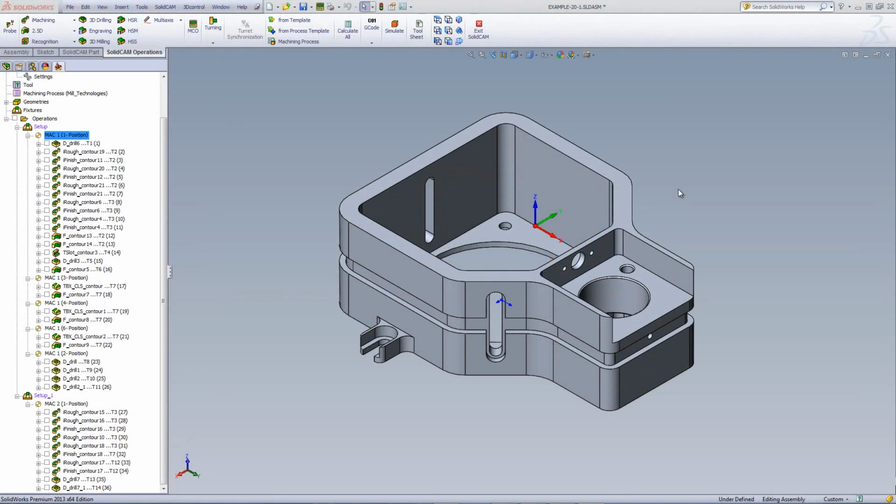In this recording, we'll demonstrate the use of 2.5D machining operations in order to mill this entire part. If we take a look at the part itself, you'll note that it has many different types of features on it. First, we have deep pockets that have to be milled out. We have holes that have to be milled out or drilled out. We have this slot around the part itself that we can use our T-slot operation to mill that out.